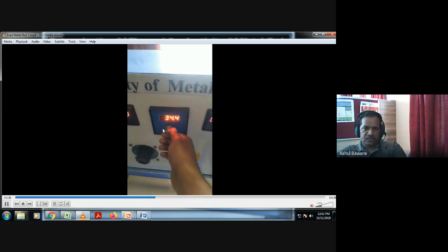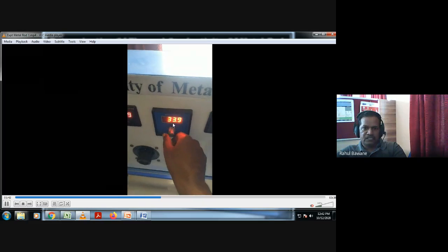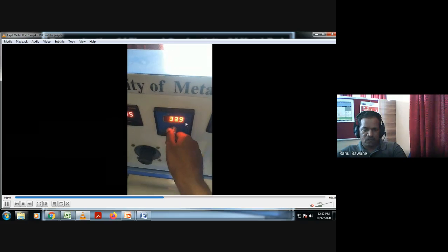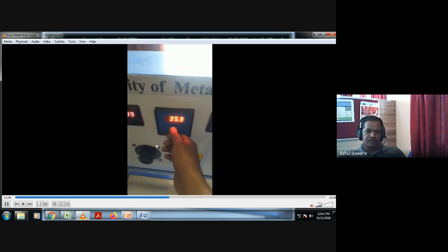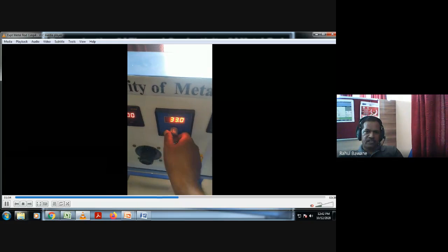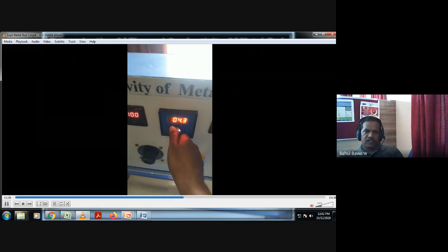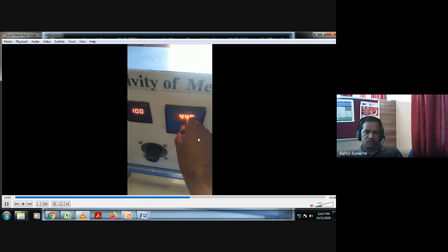As we just started the equipment, all thermocouples are in nearly the same temperature range. So we have to wait for 20 to 30 minutes so that there will be a change, because heat requires time to travel from the heating end to the cooling end. There are T11, so if you go for the T12 position, there will be no reading.